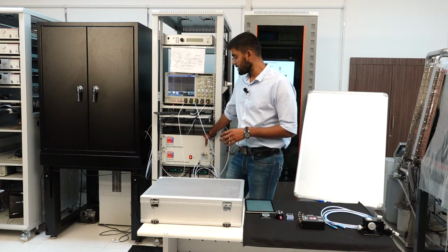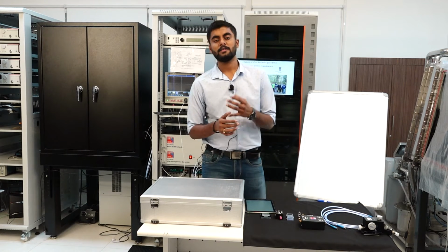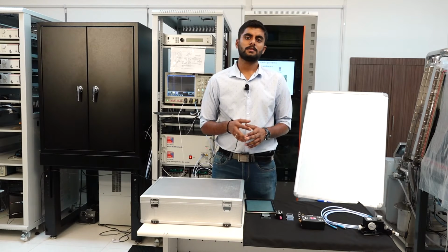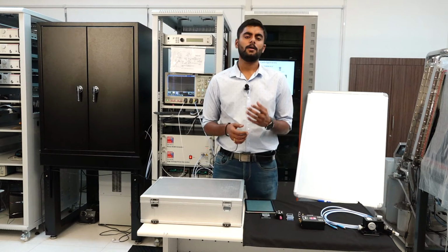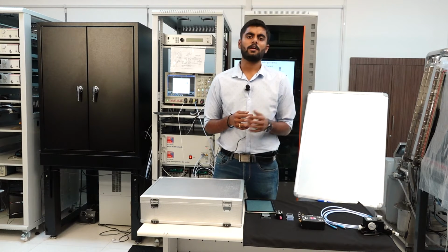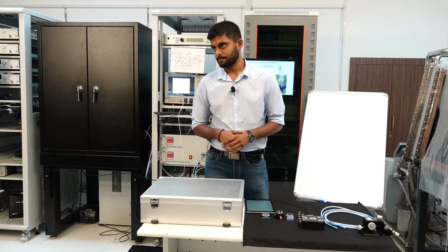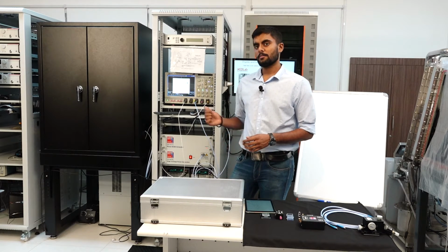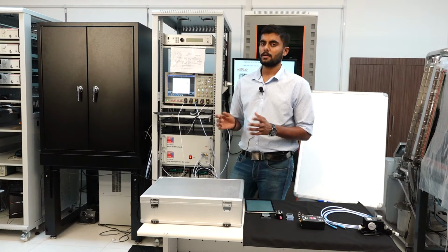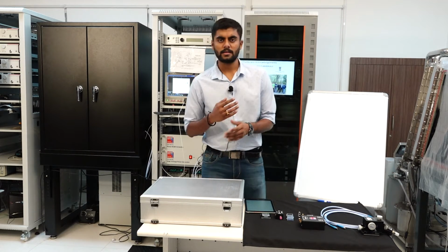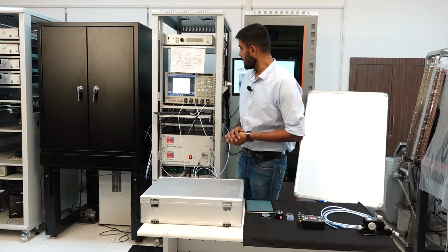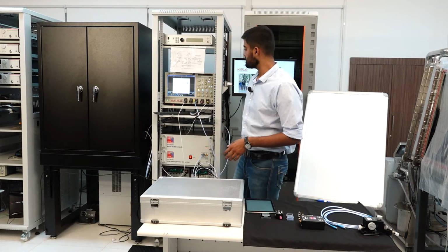The pulse width extender is then necessary because your generator in its default state cannot apply on time periods of more than 100 nanoseconds. So this pulse width extender takes the whole setup up to 1.5 microseconds, and that's why it becomes important, because then you have to do measurements for a longer time. You actually use this pulse width extender as well. These two components are connected on the back side through a common connection. So basically, the communication line between the two instruments is there, and they can synergize between themselves as to who has to get involved at what time period. So this is how the pulse width is generated.